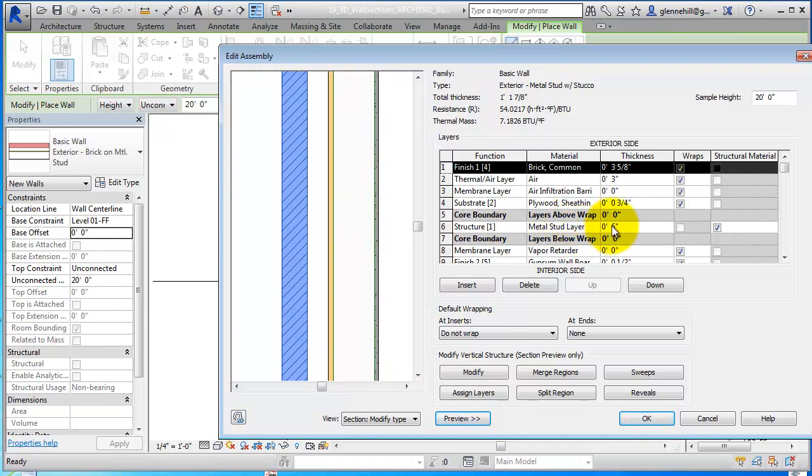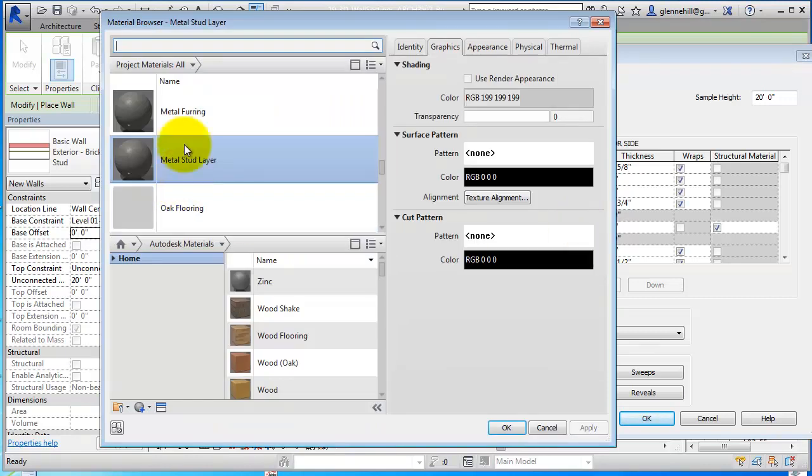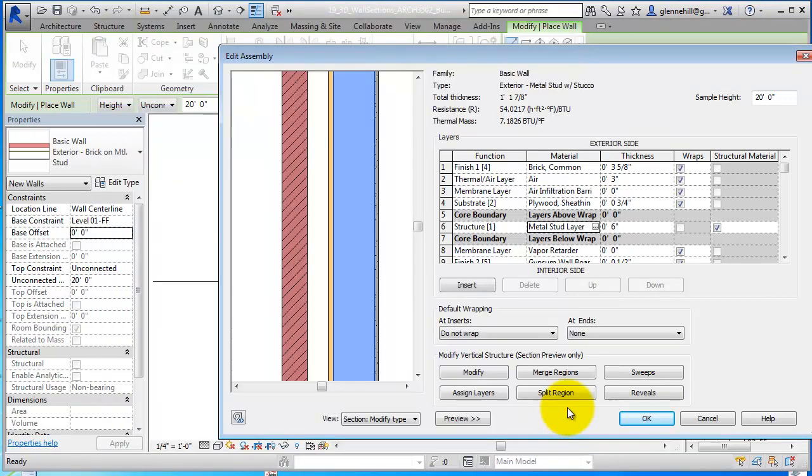And you'll see, the primary structure of this wall is the MetalStud, and that's been added as a material, a MetalStud layer, 6 inches. For this story building, 6 inches would probably be structurally sound and also give us a good thickness for putting insulation in. And you can see right here what I've selected. When I select something else, it turns blue, right? So out from that, there's a variety of different ways to build the wall, and I'll show you some examples.